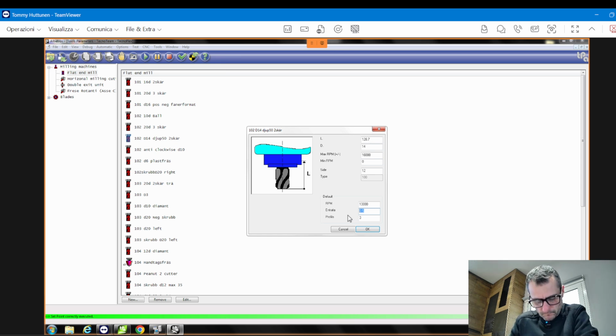Is it possible to change on AlphaCam? Yes, it's possible to change. Okay, good. To change, I must make some modification in the post-processor, but it's possible in the future if you want. For the moment, create the tool and multiply by 1,000 in AlphaCam. Okay. So in AlphaCam you multiply the fixed speed and the profile speed. So for the moment we work in this way, but in the future, yes, we will think about changing it also in AlphaCam if you want.